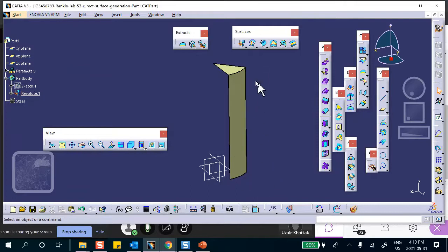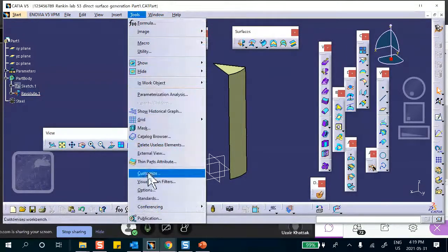So here's what I'm going to do. I'm going to create a coordinate system, an axis system. Let's find it. For an axis system, you can't miss it. It just looks like an axis. The only thing is I may have inadvertently closed this toolbar, and I honestly don't know its name. If somebody sees it, let me know. Or if you don't know it, let's go ahead and reset our toolbar. Tools, customize.